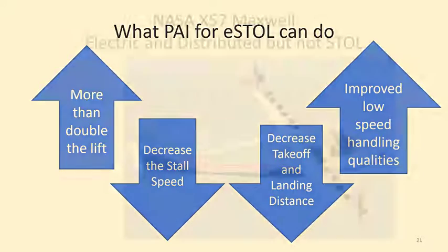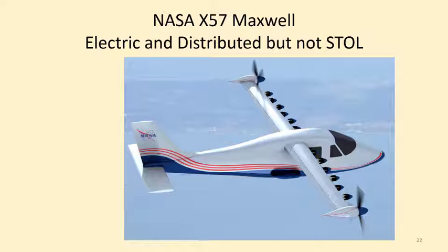This wouldn't be complete without mentioning the X-57 Maxwell that NASA is currently working on. They are using distributed propulsion, and they are getting propulsion airframe interaction, but they're primarily using it to augment the fact that they've got a much smaller wing, improving the cruise capability of the aircraft. Here, the 10 inboard electric motors all have the propellers folded because they're only used on takeoff and landing.